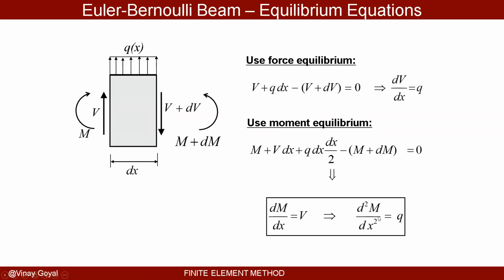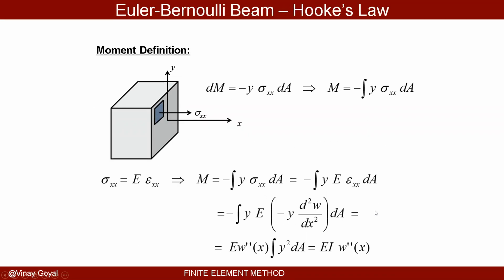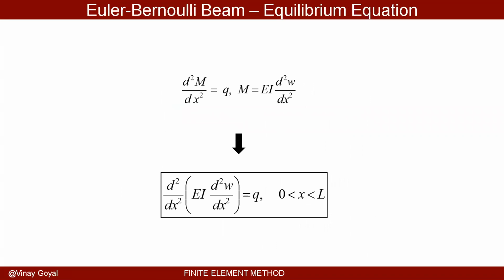All I have to do now is plug that in here into this equation to get the differential equation for a beam. This equation we derived earlier, but we re-derived it again for reminder purposes. And recalling this information is very useful because you get connected to what's going on. Here, Q is the distributed force, transverse to the beam. W is the transverse deflection. I is the second moment of inertia, and E is the modulus.